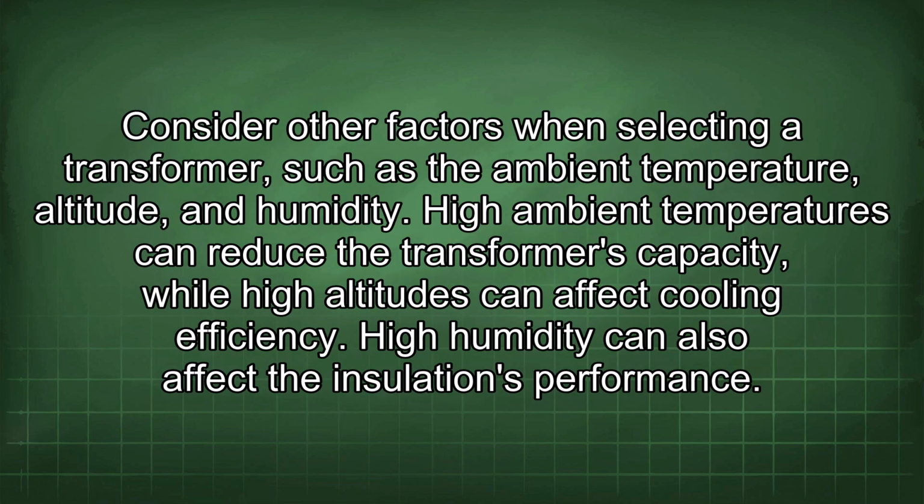Consider other factors when selecting a transformer, such as the ambient temperature, altitude, and humidity. High ambient temperatures can reduce the transformer's capacity, while high altitudes can affect cooling efficiency. High humidity can also affect the insulation's performance.